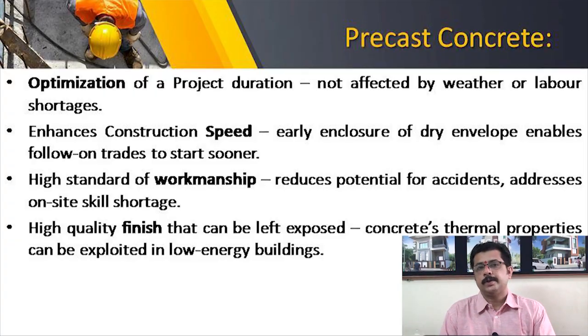Optimization of project duration is possible with precast concrete technology. How? Because in situ construction is affected by weather condition. It may be interrupted due to rains, summer or shortage of laborers. But this is not the situation with factory made product. This way it optimizes the project duration.